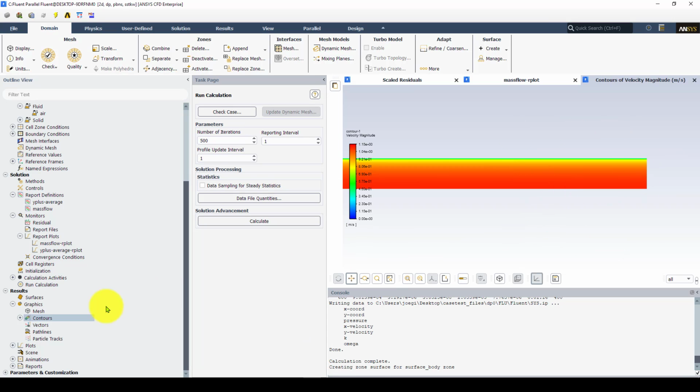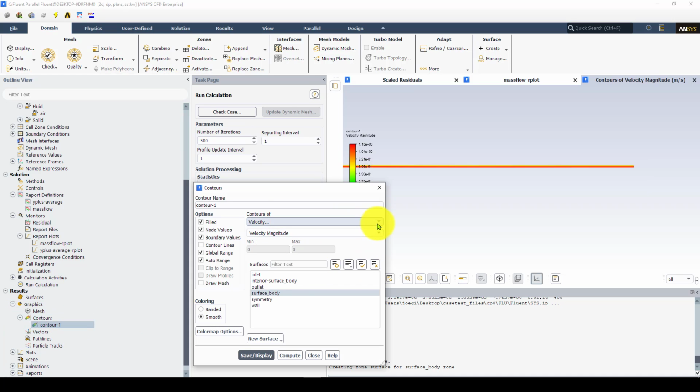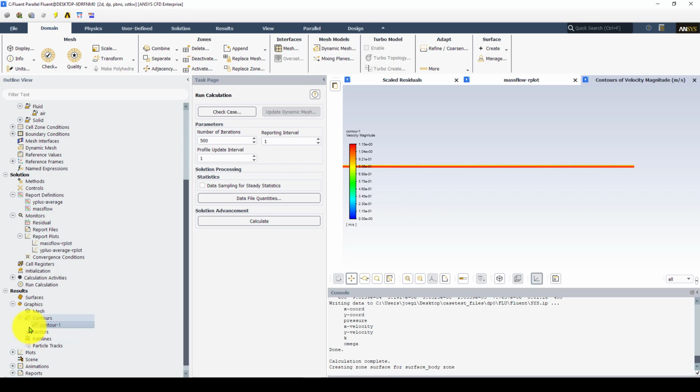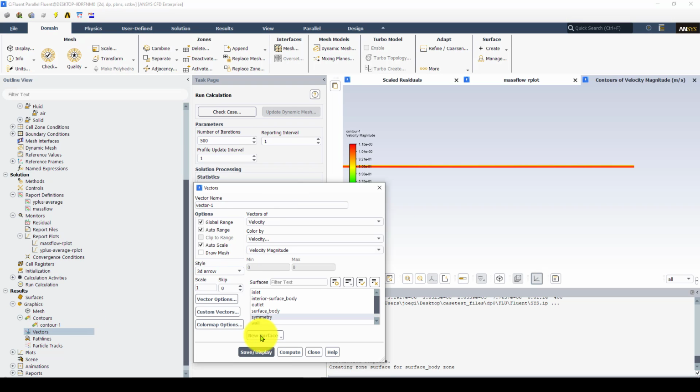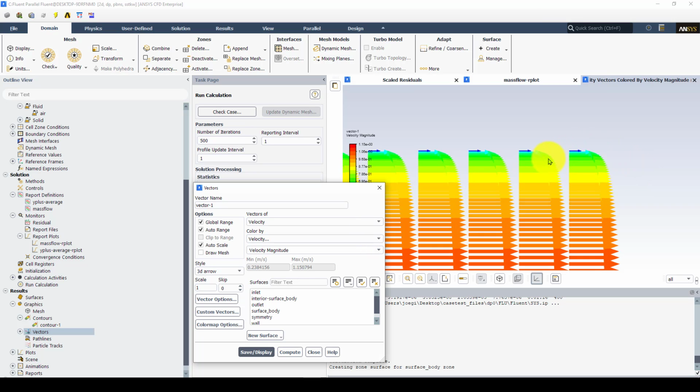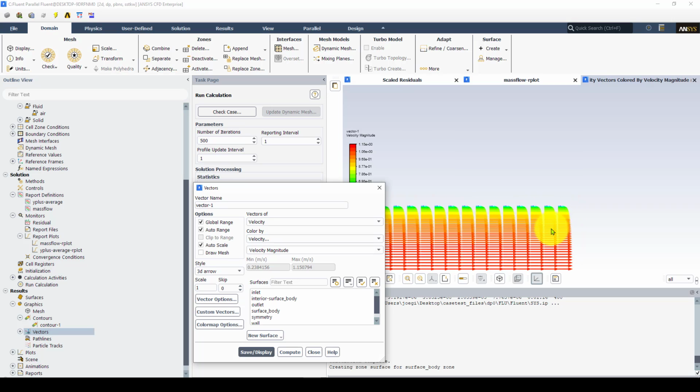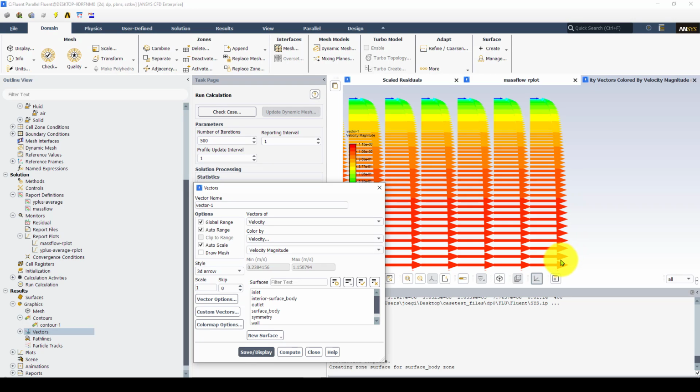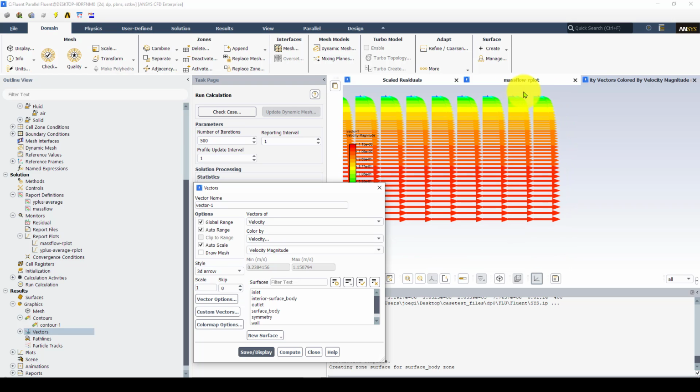Okay, again, for instance, let me go and do some other plotting. So here, you choose all your quantities. Whatever you want, you can choose it here. So you have access to everything that Fluent has computed. So you can plot vectors here. So again, you go here and zoom in and see that here we have our velocity profile. And remember, this is a characteristic profile for turbulent flow, very uniform here. And then you have these strong gradients here.